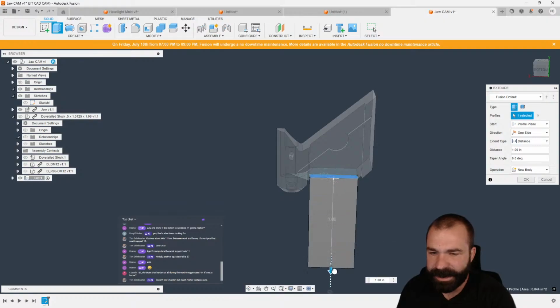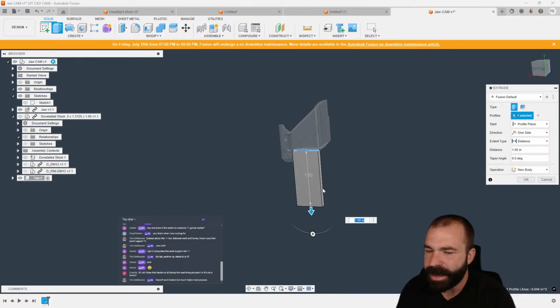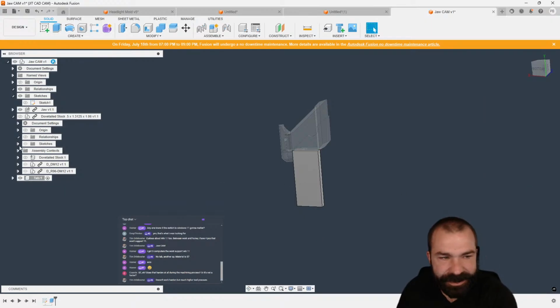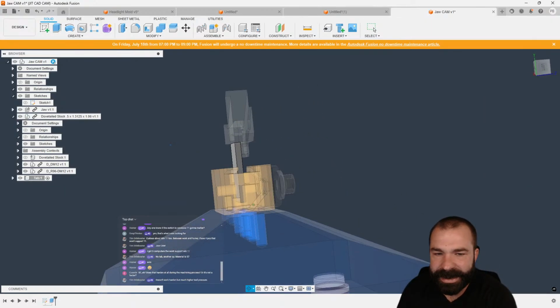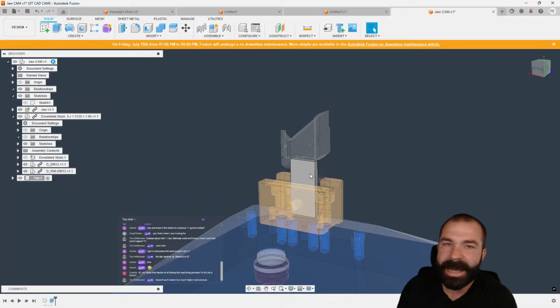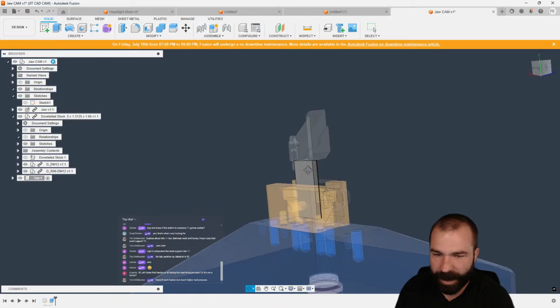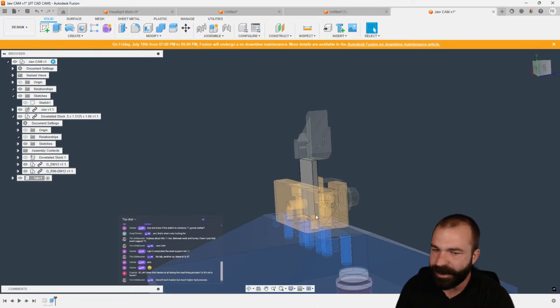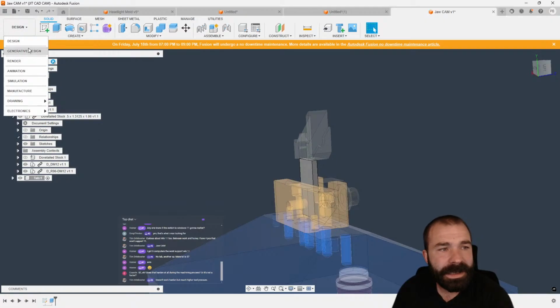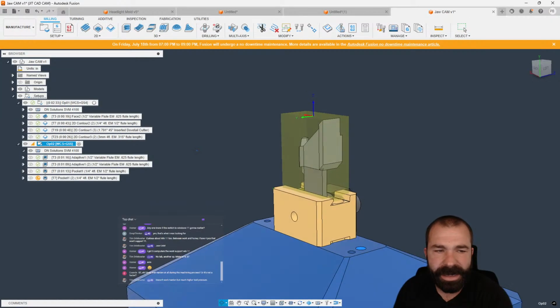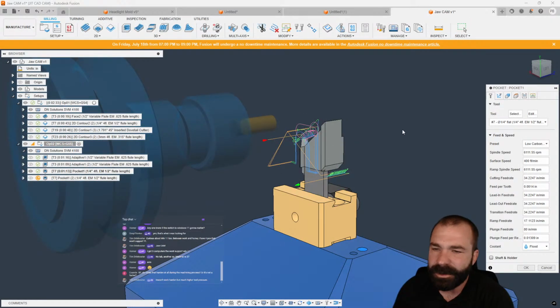I'm going to then extrude said rectangle. Now, the key element here is I can over exaggerate this actual tab, but the idea at the end of the day is I'm going to give that model of the tab to my tool path, and then it will respect that as well, right? So again, even though it's down in my jig and fixture, it's there for a placeholder. That's all it is.